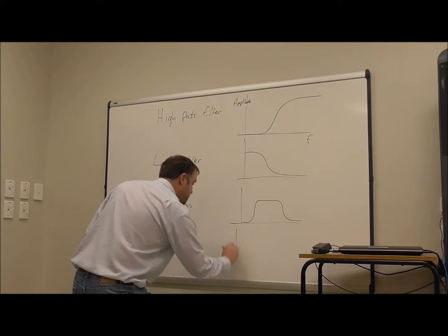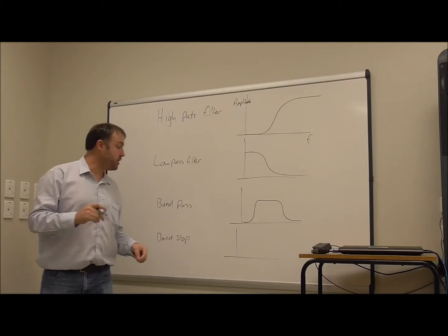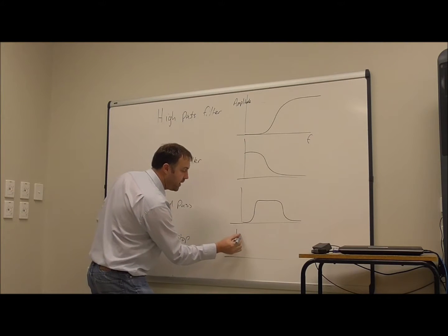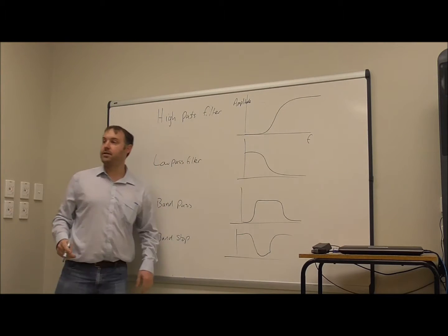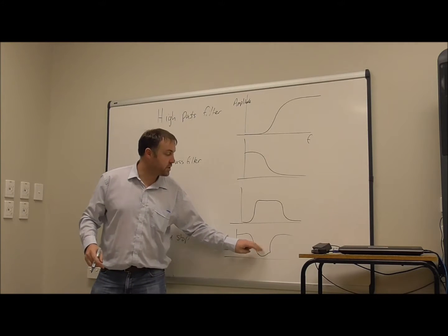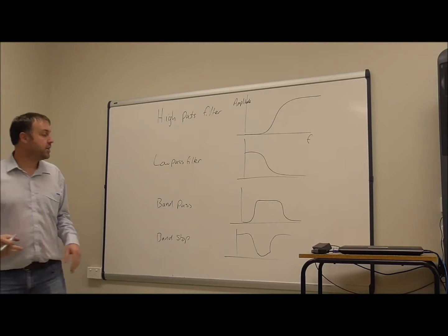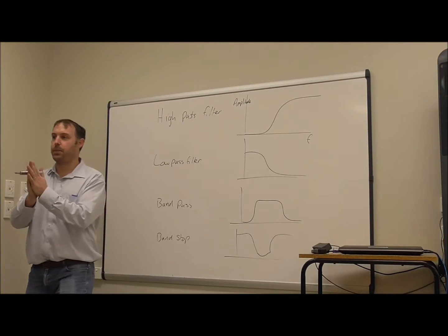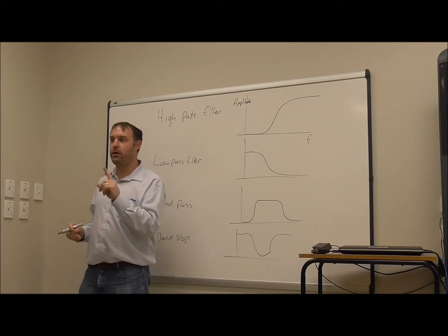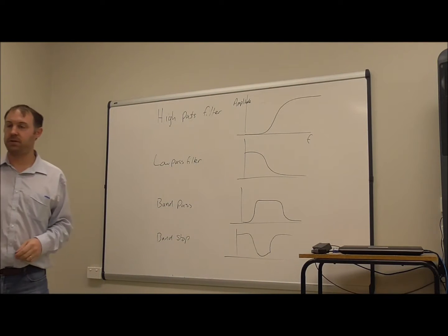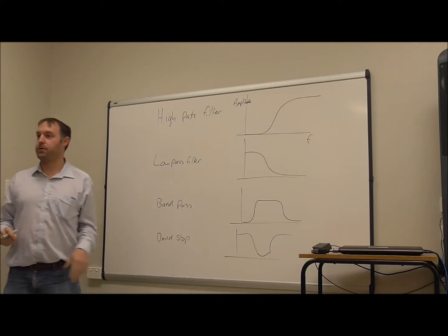As the name suggests, it will stop a band of frequencies at just one little range while allowing the others. So we have a low pass filter and a high pass filter, and with a combination of those two, we're having a stopped band. Now there are a couple of different types of band stop filters. There are general band stop filters which stop a certain range, but there is another type that we call a notch filter, and that stops a very, very narrow band at a very specific frequency. We'll be discussing and exploring these 4 different types of filters.